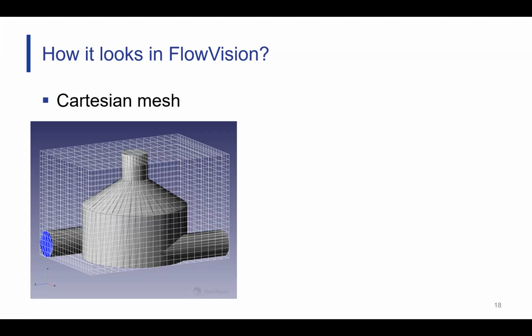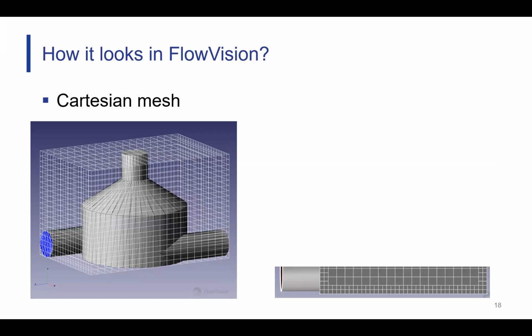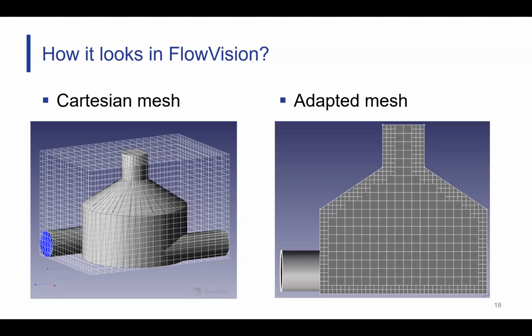The second stage we have is the refinement stage. Here we're going to be splitting the cells into smaller cells, only in the regions of interest to capture the geometry and the flow features. So notice here how more or less it's all the same, but next to the walls, we've got finer mesh resolution. Again, FlowVision will adapt automatically to the specifications that you feed it.